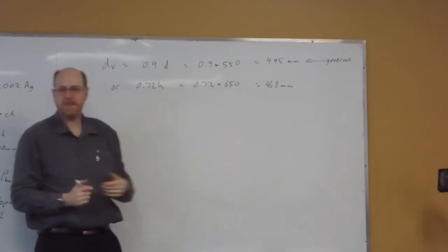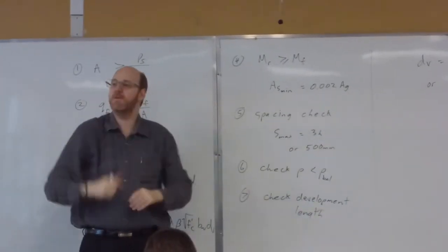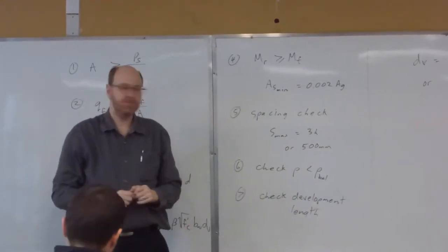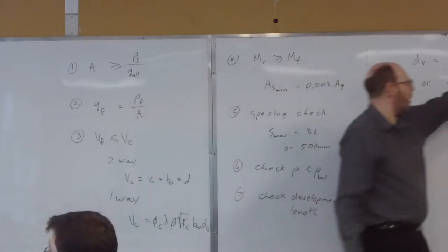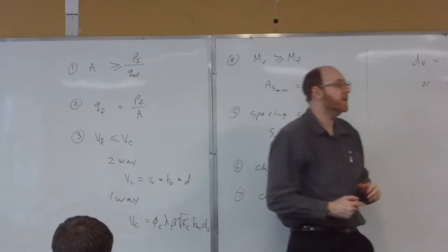This is a quick shortcut which is often used in footing design. If I'm using a 25M bar and my cover distance is 75 millimeters, I've got 75 plus 25 to get that 100 difference, and that gives me the centroid of our reinforcing steel, which is right in between the two rows of bars. So this is a shortcut approximation that is often used. Just take that number, subtract 100, and I've got a new d.